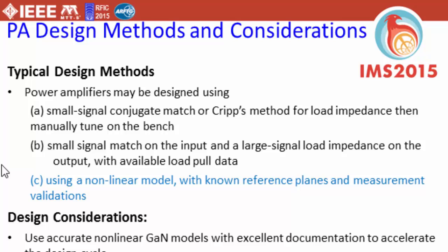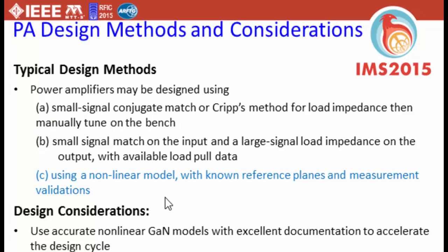Another approach is to use load pull data and a small signal match on the input, and use load pull data to optimize the output matching networks. With a nonlinear model that is properly prepared with known reference planes and measurement validations, a more flexible design approach is possible, and load pull data can actually be generated at different frequencies, even though the model may be validated only at a limited number of frequencies with load pull data.